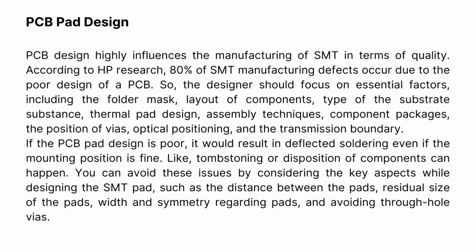If the PCB pad design is poor, it would result in defective soldering even if the mounting position is fine. Like, tombstoning or displacement of components can happen. You can avoid these issues by considering the key aspects while designing the SMT pad, such as the distance between the pads, residual size of the pads, width and symmetry regarding pads, and avoiding through-hole vias.